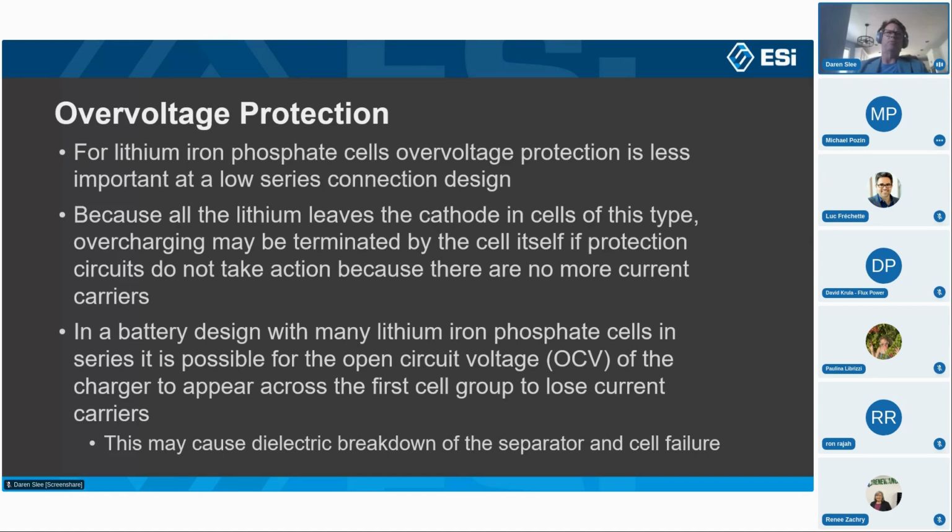You want all that capacity. So a typical output voltage without a load, an electrical load where you're conducting current, may be 0.1, 0.2, 0.3 volts higher than your end state of charge. So for a 12.6 volt battery, which is 3 series, 4.2 volts each, you may want about 13 volts to lift that battery up to that voltage, so it can actually continue to push current, and then you do your CV charge profile and cut off from your charger.